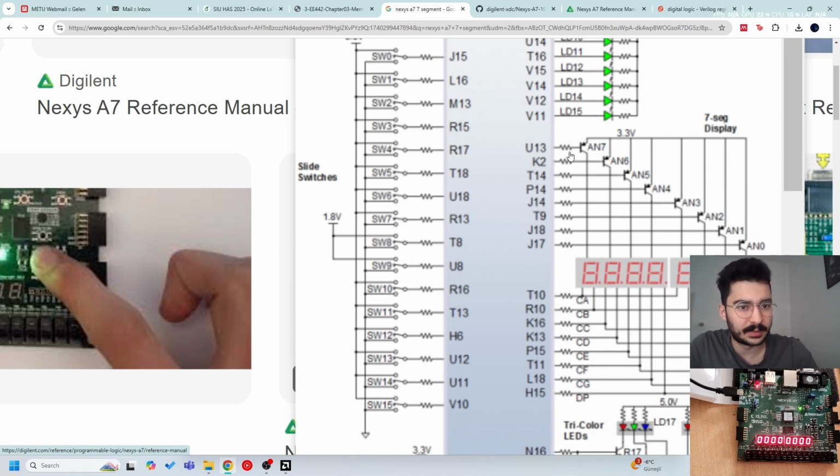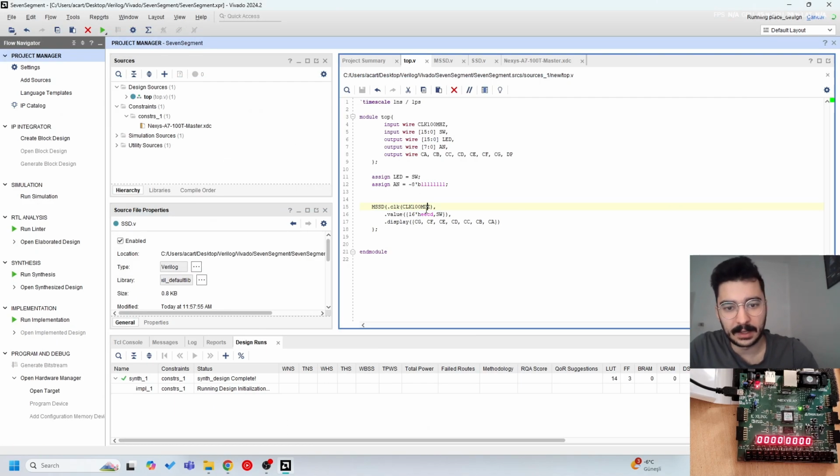Since this increases the R times C, there's always capacitance in these kinds of circuits. So these resistors increase the RC time constant, which in turn increases the time period of these connections. And I cannot switch these ports at 100 megahertz, which is a very, very high frequency.